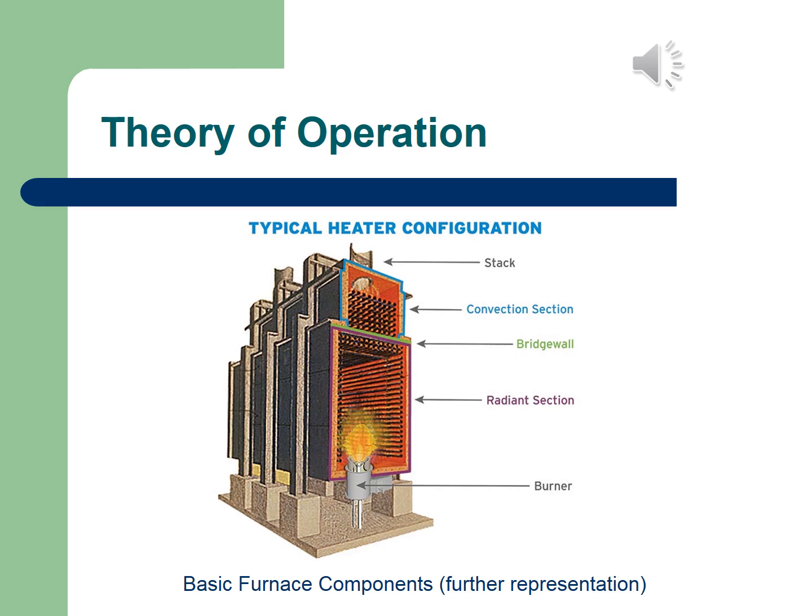The radiant section is where your higher temperature will be, and the convection section is then at a lower temperature, but the pipes containing the load are fed to the top section so that more heat can be absorbed by the load. So it makes the system more effective. So you do have these two heating sections that were not displayed on the previous figure. And then, of course, as in the previous figure, there is the burner. Now, again, the burner consists of your oxygen and then the fuels.